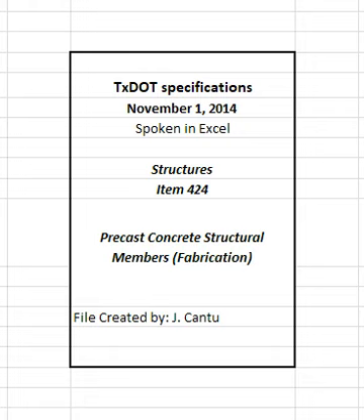Submit a plan for approval, if necessary, to demonstrate the concrete can be properly placed, consolidated, and finished without reducing placement time limits. The maximum acceptable placement slump will be in accordance with Item 421, Hydraulic Cement Concrete, unless otherwise specified.